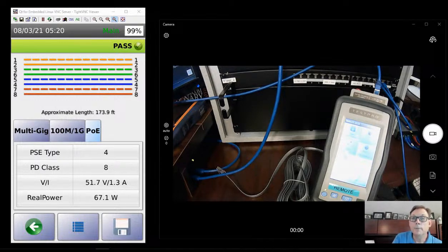So if you have a network that's functioning perfectly and you run an SNR test on it and everything on there is showing up at 6 or 7 dB, then that needs to be your benchmark, because maybe you want that to be your bottom line. But 3 dB, once it starts getting below that, the closer you get to 0, the more issues you're likely to have.